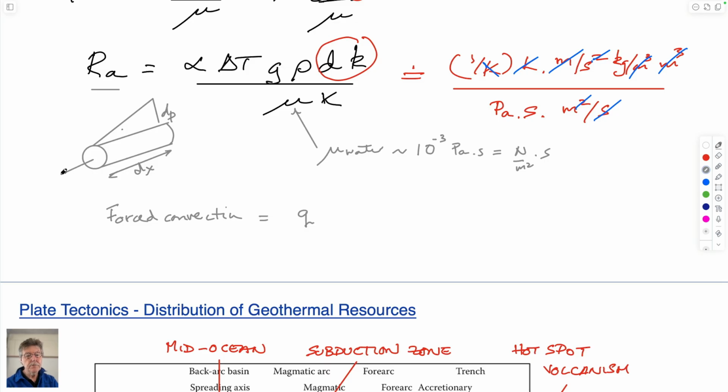And so this would give you what we've defined as Q of water. From Darcy's law, we could write that Q water is equal to minus K over mu dP dx. So if we know the permeability, viscosity, and the pressure gradient, we can get this. If we multiply this by the cross-sectional area, then the volumetric flow rate is equal to Q_w times area.